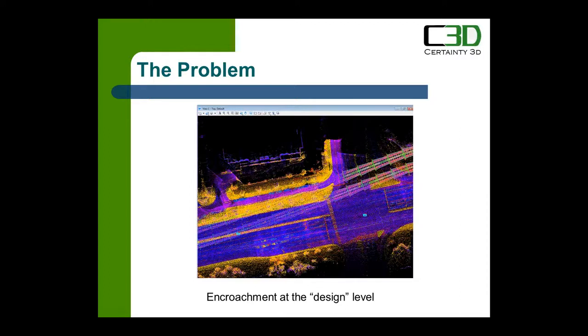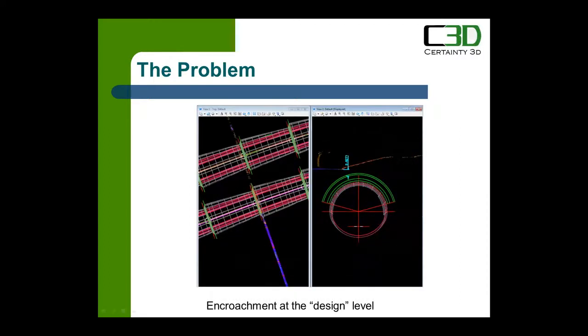So I did a quick analysis in TopoDOT, with tools we've long had, where we can basically click on the center line, cut a cross section, and you can see where the dimensions are getting too tight here. There's a little under 3 feet, or probably sideways, I measured wrong, but about 3 feet from where the tunnel would be, and this should have been 10 feet or so by spec. So they had to basically remove that tunnel path and adjust that. Okay, so this can be done in TopoDOT.